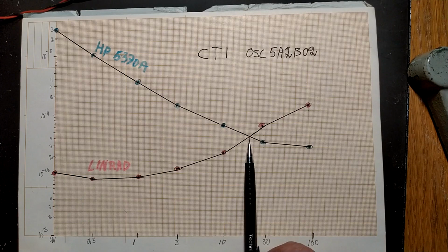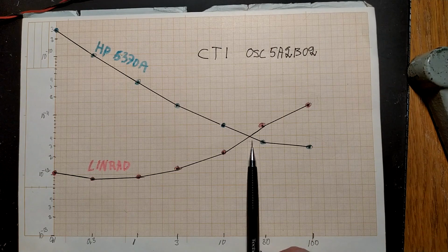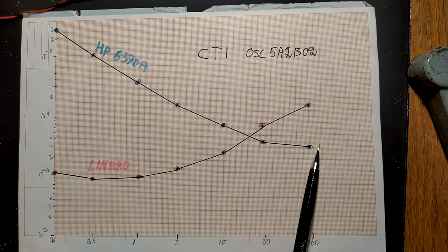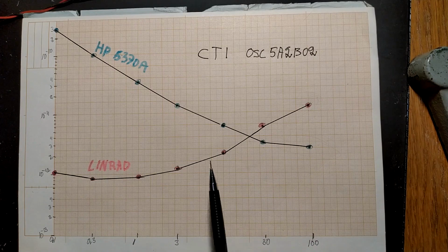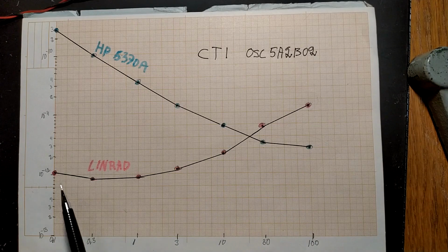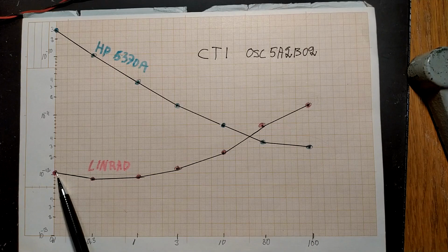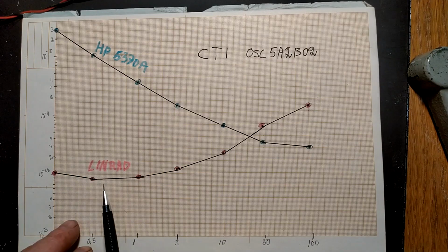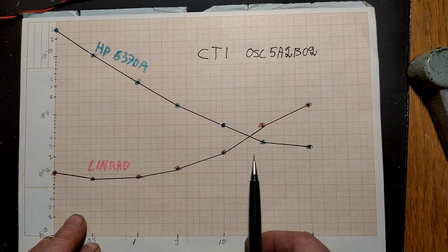And here, when the lines cross, maybe the truth is a little bit below here for a curve that looks something like that. Or maybe it looks like this. Anyway, this point is not right either, because I have a bandpass filter in Linrad that starts to remove data that is too far from the carrier. So actually what I have in Linrad is a modified Allan deviation. Maybe the truth is something like a line like that.